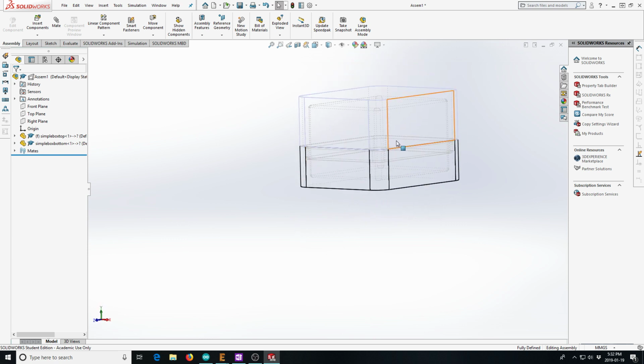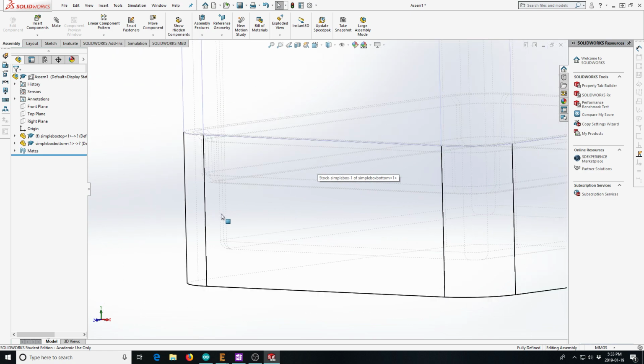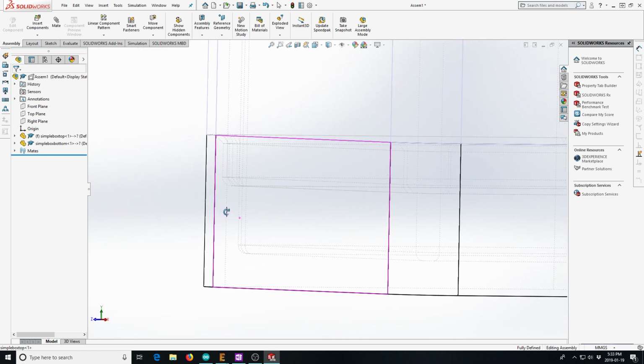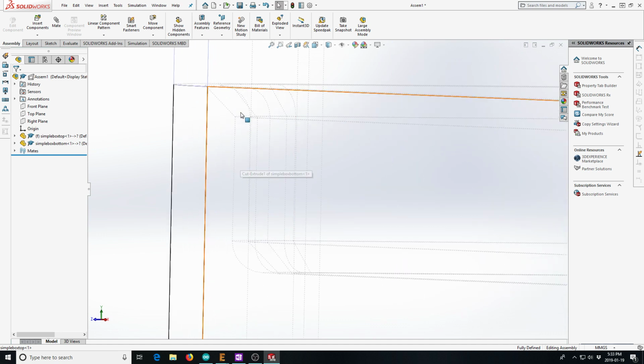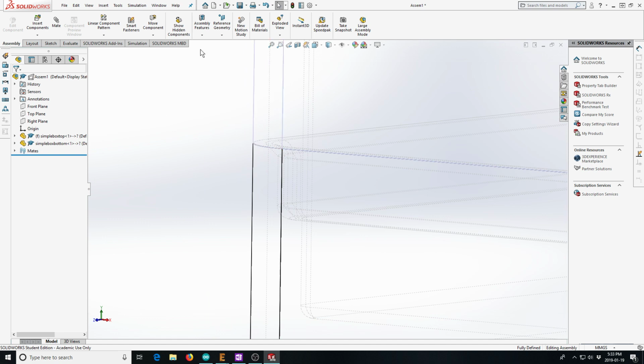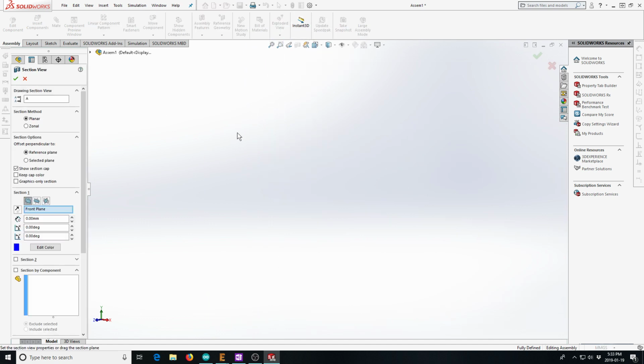And what's more important is that you can focus in and decide if you're happy with those clearances. So for instance, I made the chamfer and the fillet such that they fit together. Now one nice way to inspect this is you can pick the section tool, and we'll pick it on the front plane. That's good.